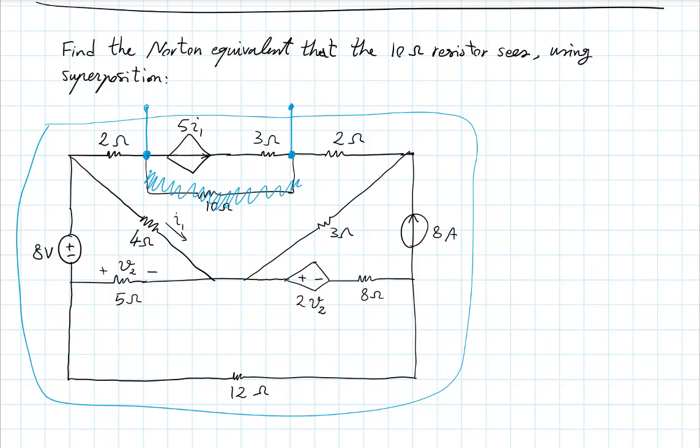Now, if we are interested in the Norton equivalent, we are essentially trying to establish the IV characteristics, that straight line that crosses, in general not the origin, but the current and voltage axes at 2 distinct points. One way to find the equivalent, as we've talked about before, is to find the open circuit voltage and short circuit current.